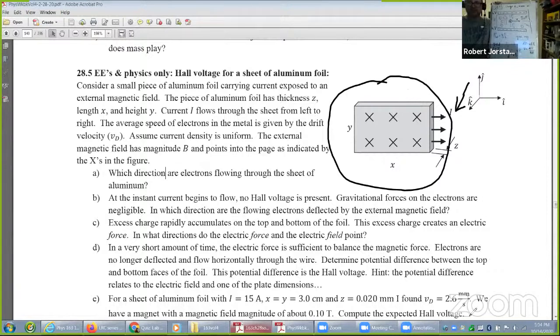And so this voltage is very special. It's called the Hall voltage. It's always in every physics textbook somewhere. When this sensor is used to measure magnetic fields, it's called a Hall probe. And so this is a standard device for measuring magnetic fields. If you're ever wondering, how do you measure a magnetic field anyways? You get a Hall probe, stick it in the magnetic field, and it runs a little current through there, and it tests the Hall voltage, and from that, it back computes the B field. So that's kind of neat.